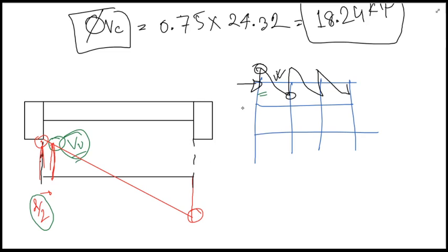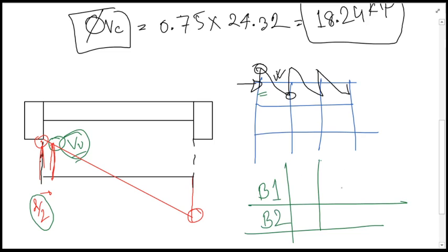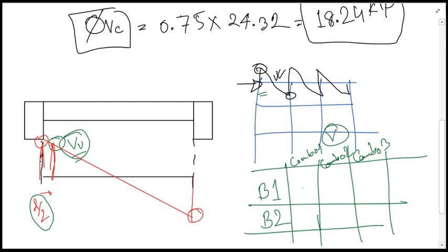So what we'll be doing, we have different combinations, and for different combinations we will be taking the maximum of those combination values as the maximum governing shear for the particular beam. And for all the beams, say for example for beam 1, for beam 2, like this, you might have got from combo 1, combo 2, combo 3. So from all this you will be getting the shear values individually.